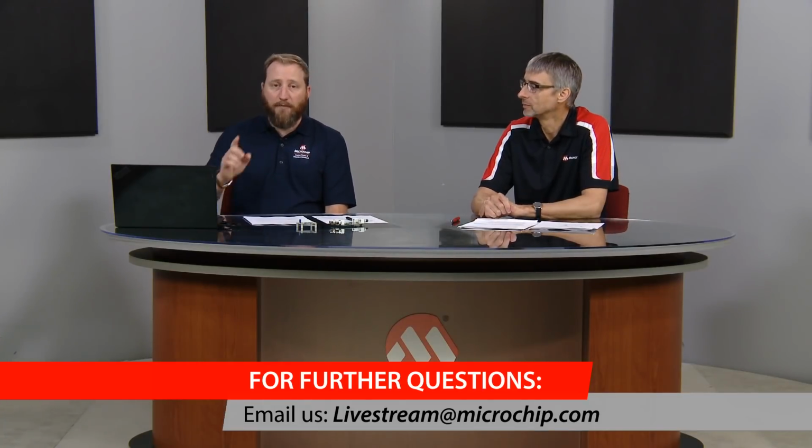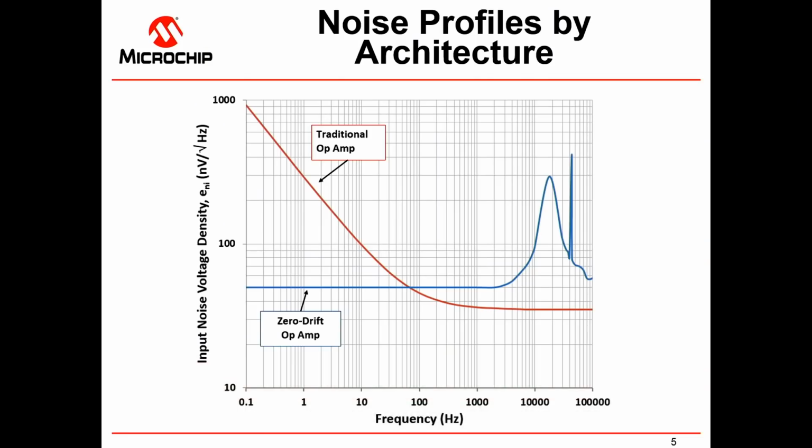Okay, so if we could go back to the chart, I believe what they're talking about is for the traditional op-amp that we're showing here. They're talking about the flat band or the white noise region, where the 1/f noise is no longer the dominant noise source, so higher up in frequency. And as you can see, just on this particular graph, the traditional op-amp is shown as being slightly lower than the zero drift. The question is, is that always the case?